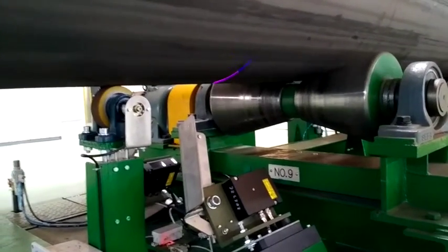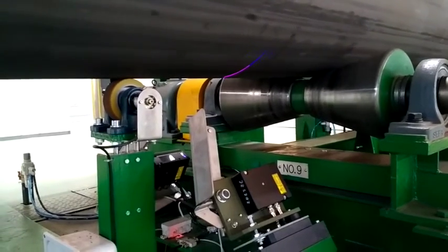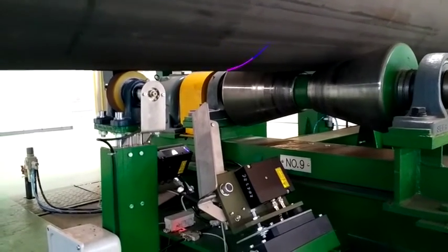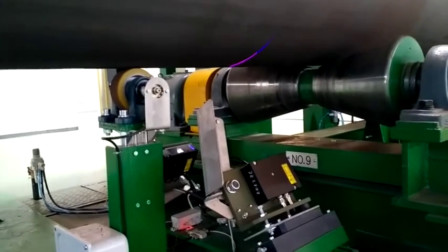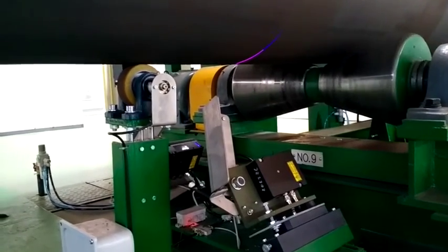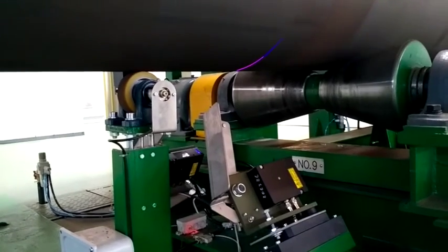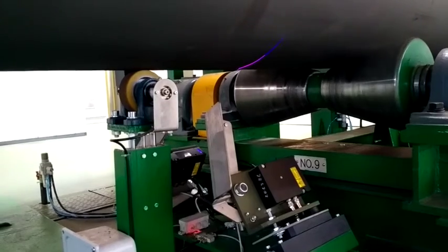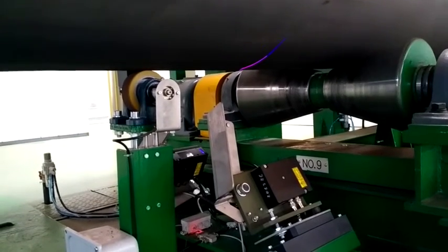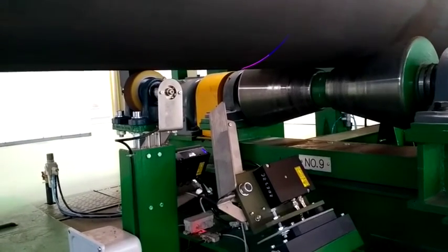The system allows to measure the following parameters: weld measurement, left and right pipe ends, including diameter, pipe end roundness, bevel angle, wall thickness of the pipe, bevel dulling and cutting angle, pipe body roundness and pipe diameter intersection, general pipe warping per 1 meter, and pipe length.